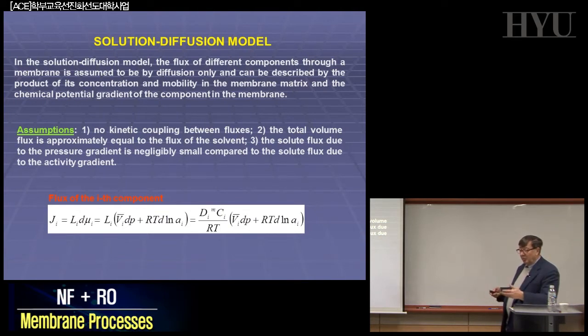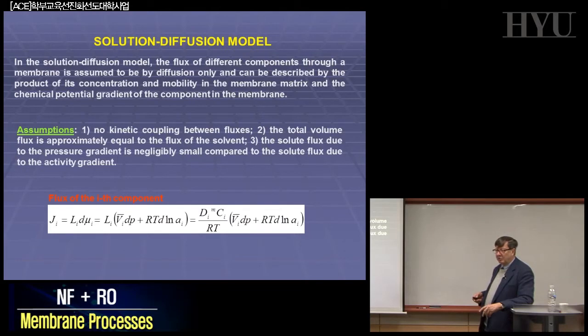And if you do this calculation, Rautenbach, Gluckau years ago made this calculation, you can find that the ions prefer to stay outside and not inside. And that can be the origin of the selectivity. But it's much more complicated to predict. This model is relatively simple, and 95% of the experimental results that we have today can be well explained using this kind of mechanism.